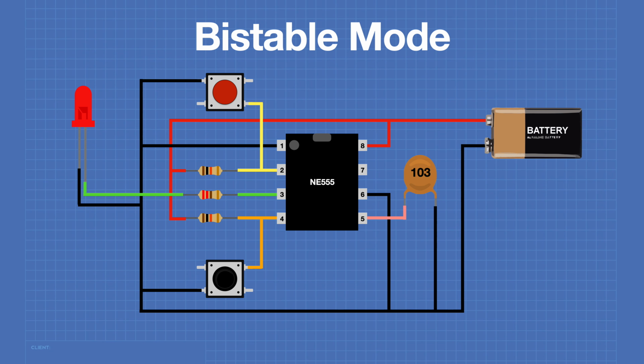As we did in our previous experiments, we'll be using the 0.01 microfarad capacitor on the control voltage input in order to smooth the voltage. And we'll be driving everything with a 9-volt battery. So let's wire that up and take a look at it.